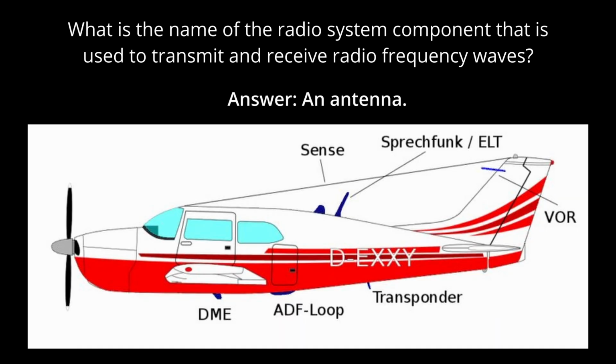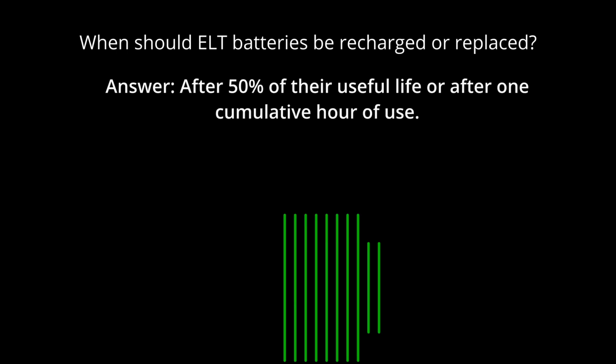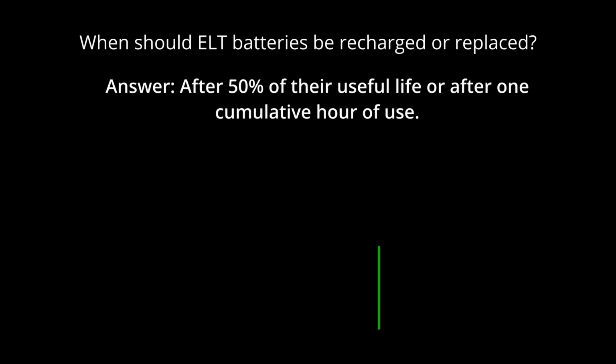Antenna. Now, y'all should review your antennas, point them out on aircraft, what they do, 'cause you may have to do that. When should ELT batteries be recharged or replaced? 50% of the useful life, and what else? After it's been used for an hour.